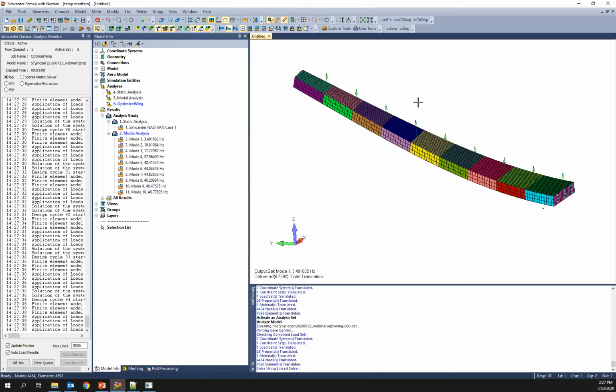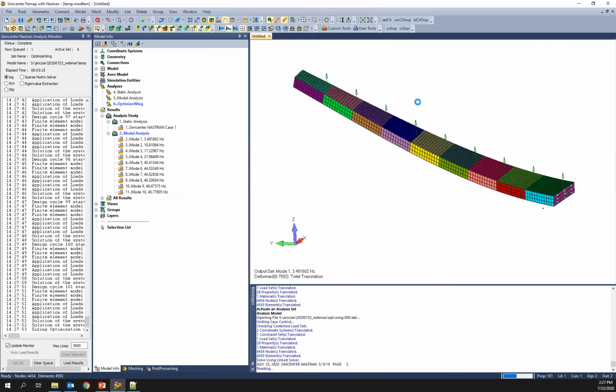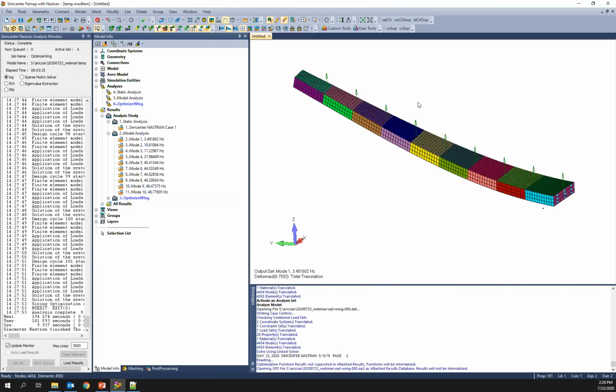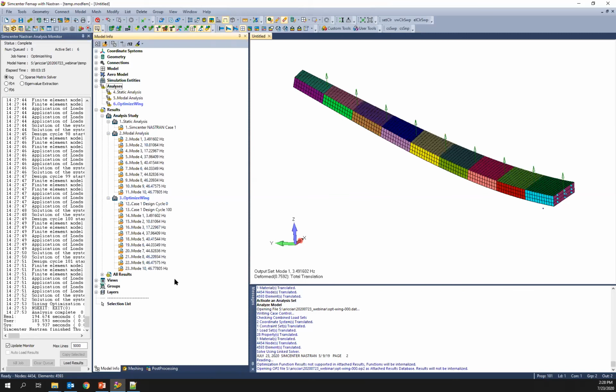In this case, I don't have the gravity load applied. Typically on a maneuver load, you may take advantage of the inertia relief effect and use that to your advantage. I haven't done that here. The wing is pretty light comparatively, since I'm also assuming there's a fairly heavy aircraft attached to this, the inertia relief effect is maybe not as important as it may have been otherwise.